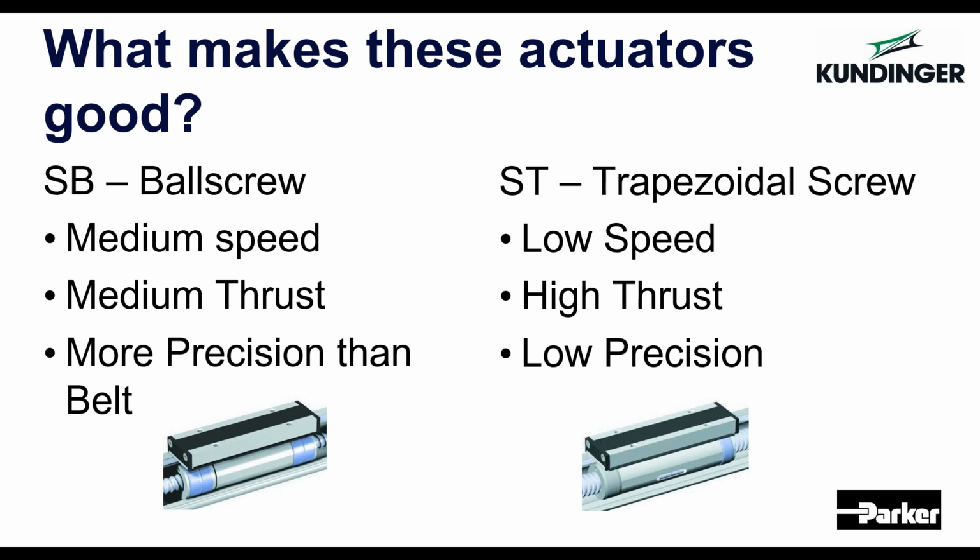So let's talk for a second about vertical applications. There's a lot of people that are afraid of putting belts in vertical applications because of that sort of belt break mentality. We put belts in vertical applications all the time. Again, I've said we've never had a belt break before, and some of our products specifically designed for vertical applications do use belts as the primary drivetrain.